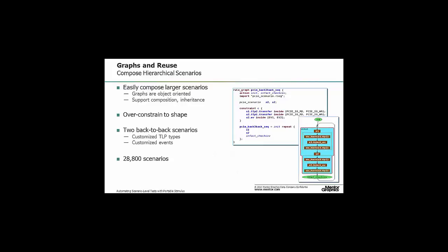This is a cross coverage, or as it's called, a path coverage. So this instructs the tool that it should systematically exercise all the different paths through this sequence that we see here. So it's actually done either graphically by adding this on top of the graph, or you can input this as a spreadsheet as well.